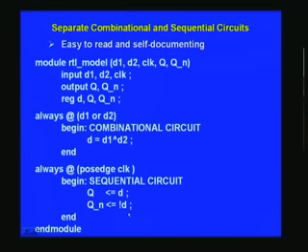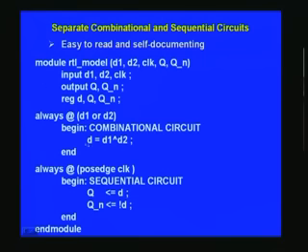A module is something like a black box. You have a block diagram which you are already familiar with. It will have IOs, and that's precisely what you have here. So that block can be given a particular name, and the block itself we call here a module. And once you have a module, you should signal to the tool that is going to process further by another corresponding keyword called endmodule. Note that there is no gap between end and module, it is a single word. So module, endmodule, this is the vital thing that you have to keep in mind.